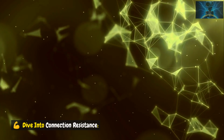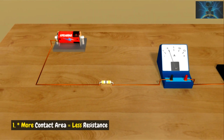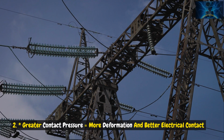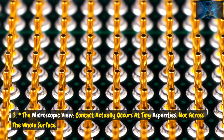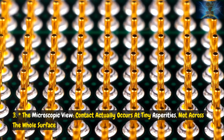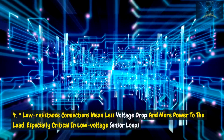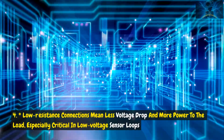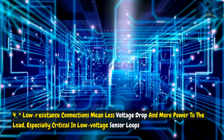Dive into connection resistance. 1. More contact area yields less resistance. 2. Greater contact pressure equals more deformation and better electrical contact. 3. The microscopic view: contact actually occurs at tiny asperities, not across the whole surface. 4. Low-resistance connections mean less voltage drop and more power to the load, especially critical in low-voltage sensor loops.